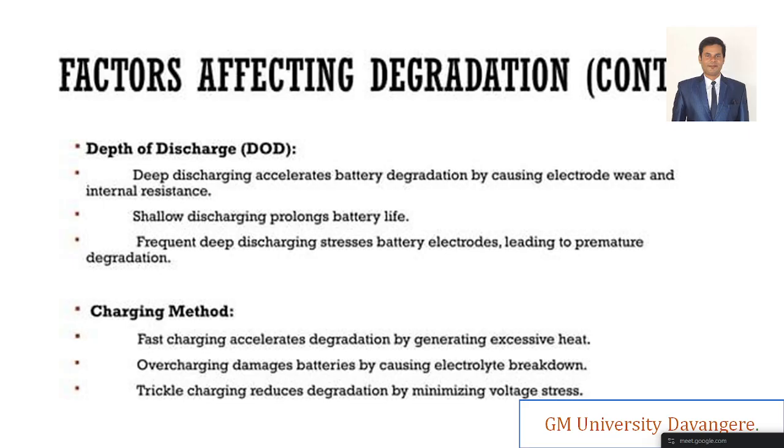Please understand the concept of depth of discharge. Depth means very inner, coming to the lower values. Depth of discharge means come down to at least 20%. Go down to 50%, 30%, 20%, or 10%, then you go for charge. That is shallow discharge, which prolongs the battery life, and it will not put more stress on the batteries.